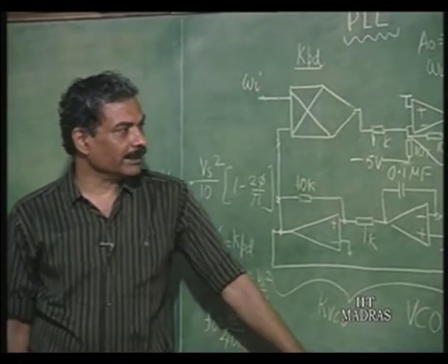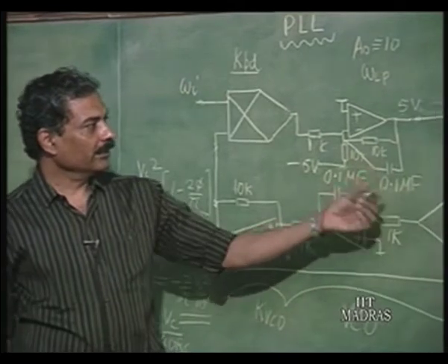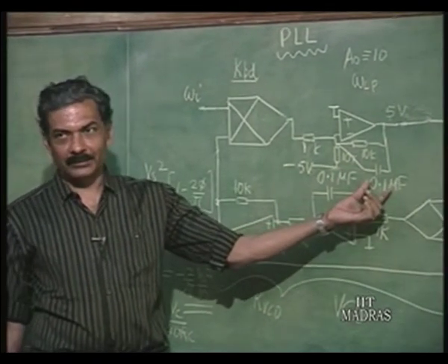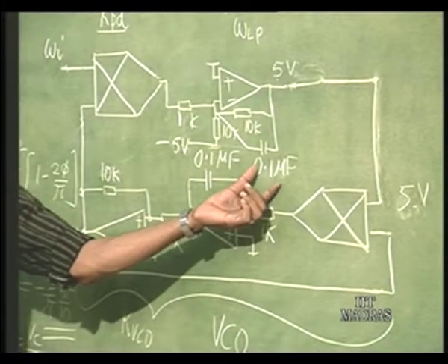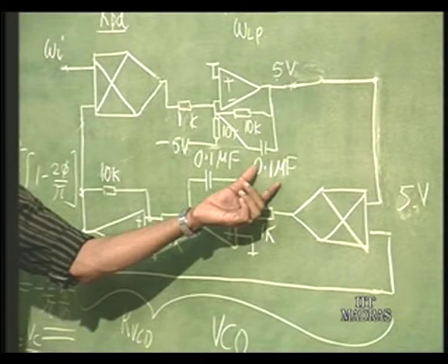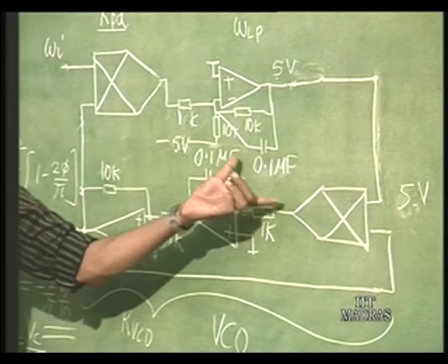And show the right. It is still locked, but with multiple harmonics. It has gone out of lock. So, this demonstrates clearly the ability of the phase lock loop for harmonic locking. In the earlier demonstration, we had put for the low pass filter across this 10K and 0.1 microfarad. This low pass filter time constant, which is 10K into 0.1 microfarad, really fixes up the dynamic performance of the phase lock loop.